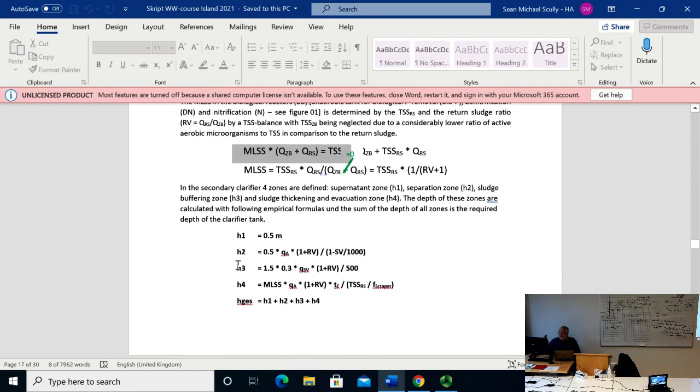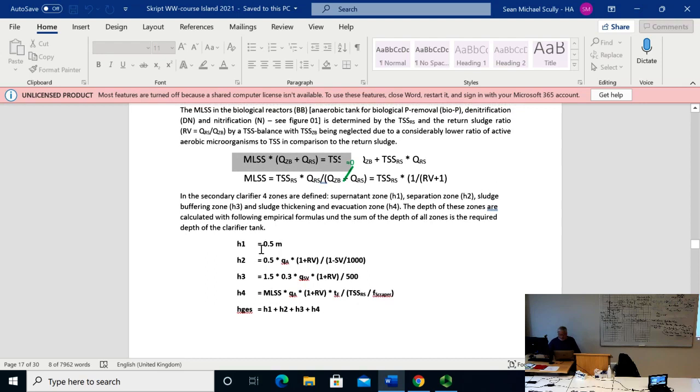So what I did, what is different really in the norm, is you should not use the 175 here. You should just use 100 liters, because here you should use ZB. Since it's empirical equations, you always have to be very careful what the relation is. They don't take all the sludge, because they consider that the return sludge that goes out here has not to be considered as a surface load.